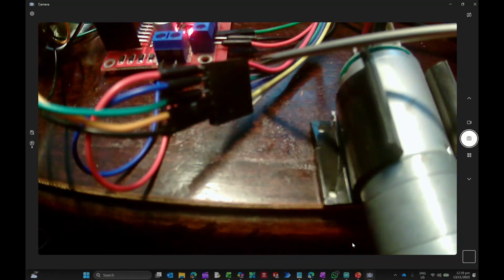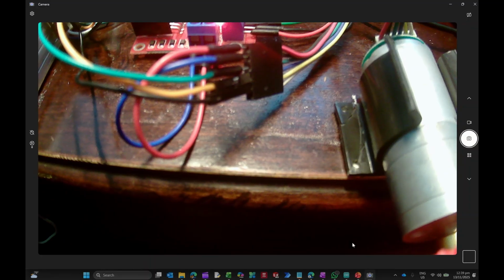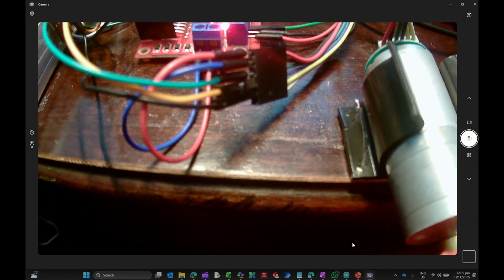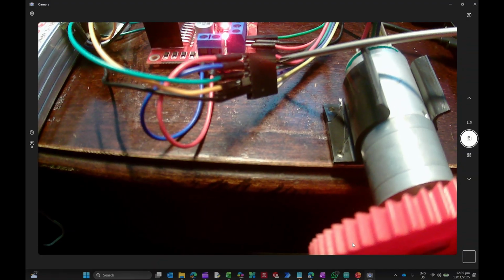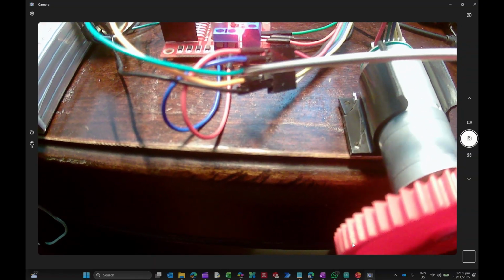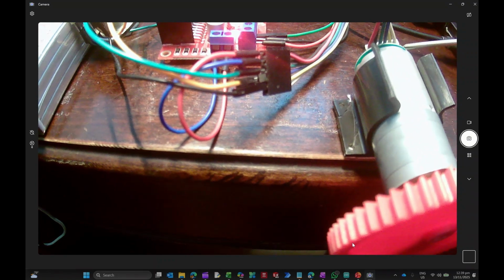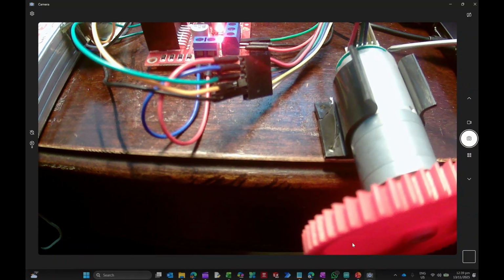You see the red, so this is the input to the motor, and the input to the motor could be anywhere. It just depends on the motor specifications. In this particular case, it goes from about 5 volts to about 12 volts DC. Then you have the ground to the motor. And from there, you have the encoder ground. So this green one here is the ground to the encoder. Then you have the orange one, which provides the power to the encoder. This has to be separate.